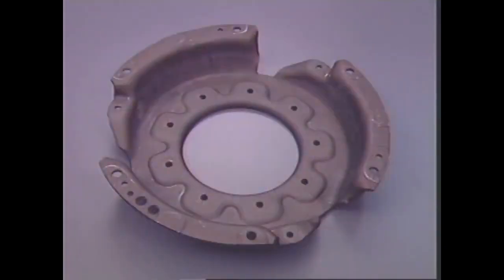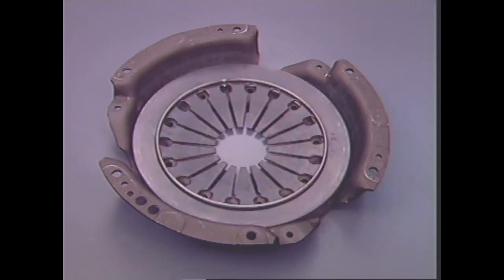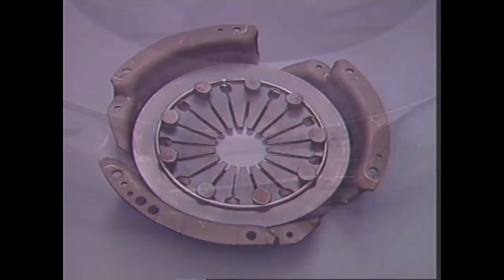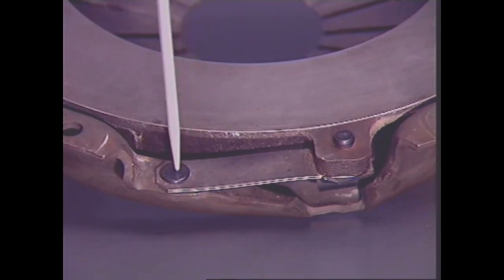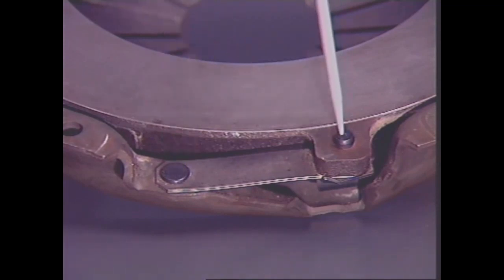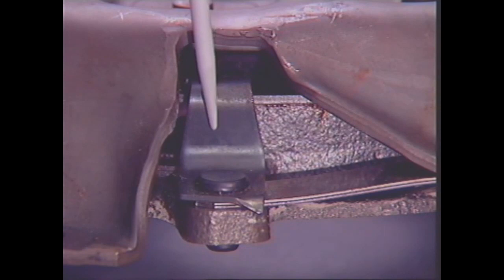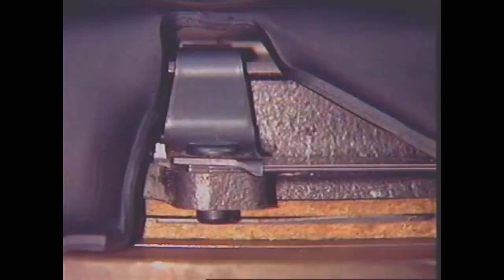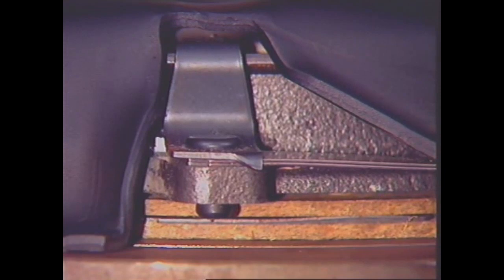This diaphragm is located inside the clutch cover on 2 fulcrum rings, held by a number of rivets passing through the diaphragm. The pressure plate is connected to the cover by the spring steel drive straps, riveted to the cover at one end and to projecting lugs on the plate at the other. Retraction clips hold the pressure plate in contact with the outer edge of the diaphragm. During clutch operation, they move the plate away from the flywheel.